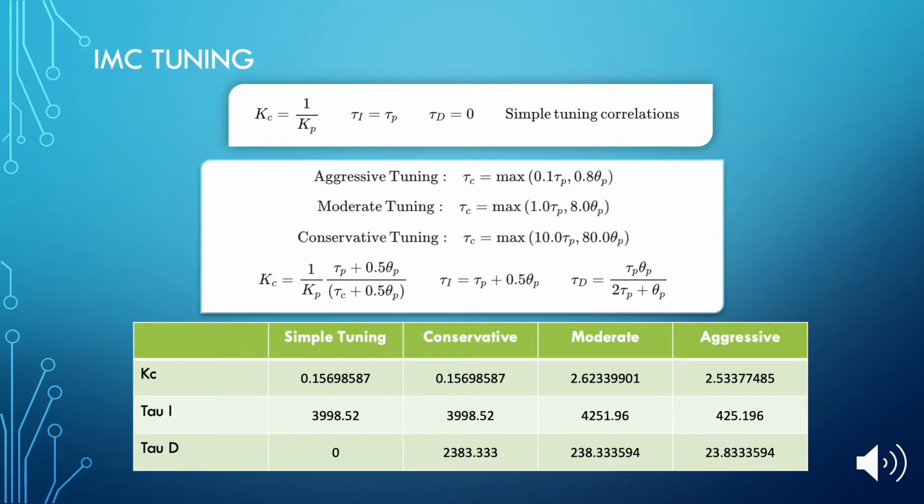And due to the low responsivity of the system, having a more aggressive model is not necessarily the right answer, as the heat transfer rate is the limit to the system, and the valve, and thus the heat rate, can only be so high. So even if the system is more aggressive, it can't go any faster.